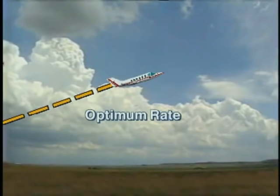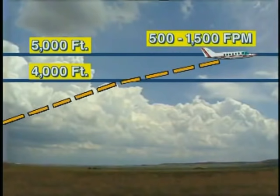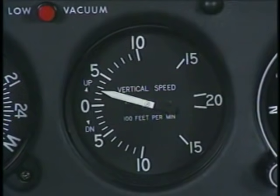When climbing to your assigned altitude, ATC expects you to climb at the optimum rate for your aircraft until you're within 1,000 feet of your target altitude. Then, slow your rate to 500 to 1,500 feet per minute until you begin to level off. If you cannot maintain at least 500 feet per minute throughout the climb, you must notify ATC of your actual rate.